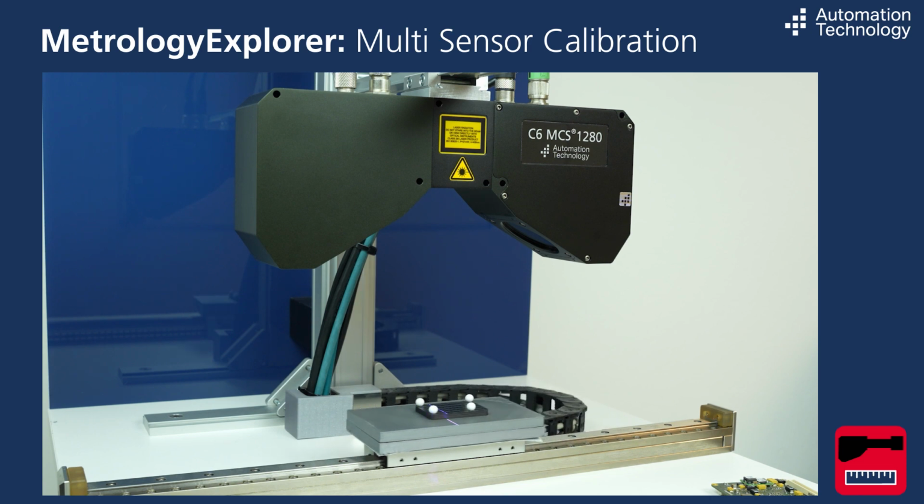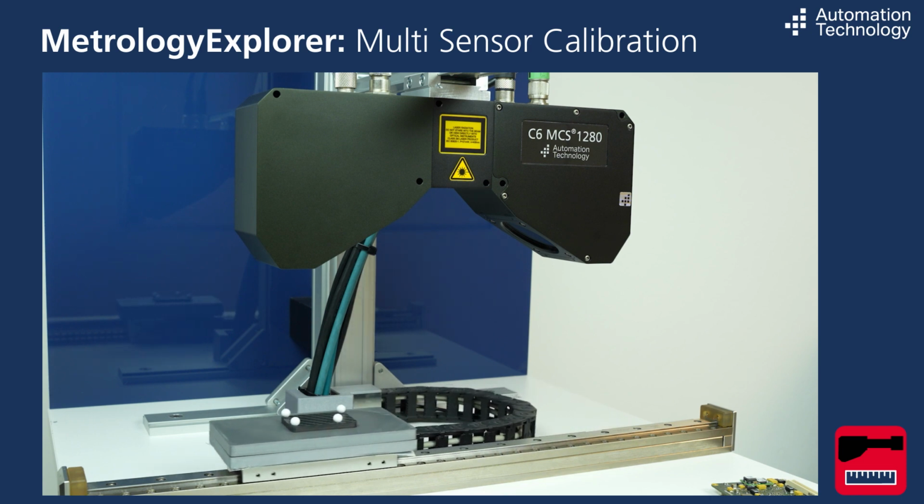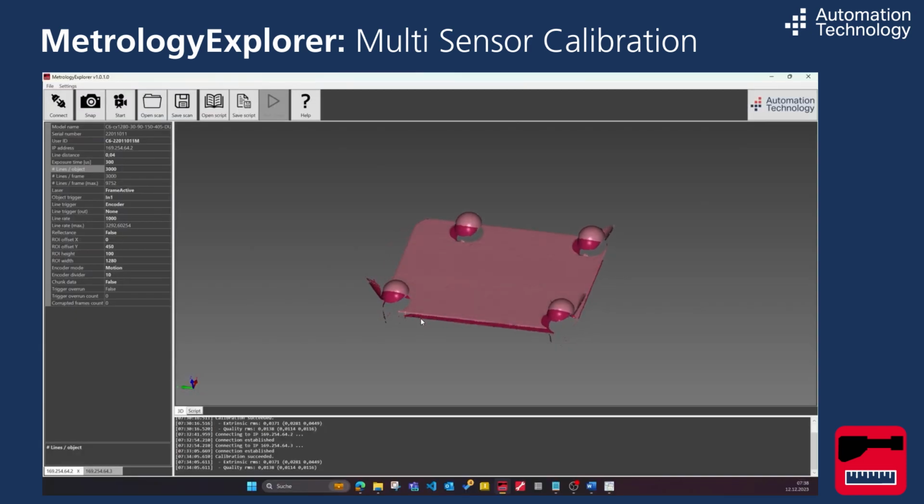The length of the object can be set with this parameter. The sensor mount is now ideally coordinated with the transport movement of the axis. Note, these reflections are likely to happen if the exposure time is set too high. With the function of the multipart object reflectance, you can check in the scan whether the exposure time is set appropriately.